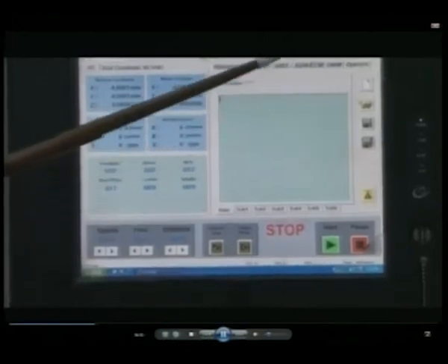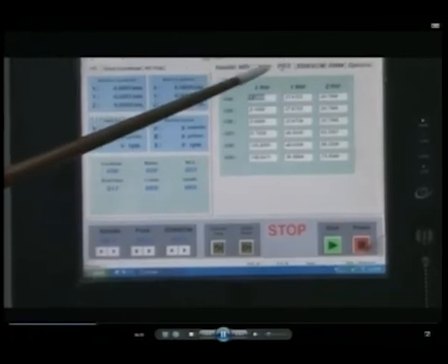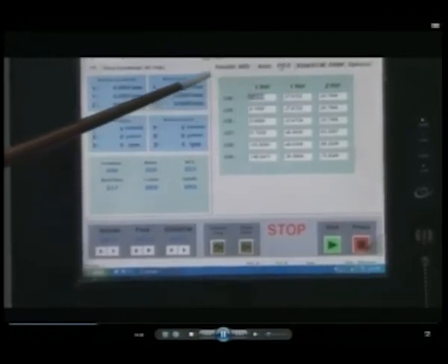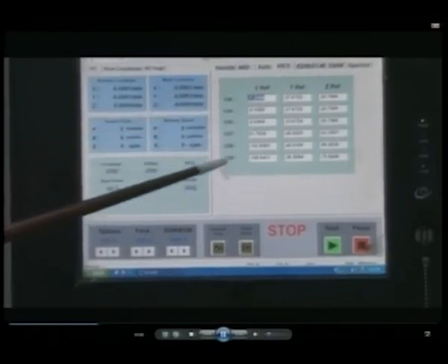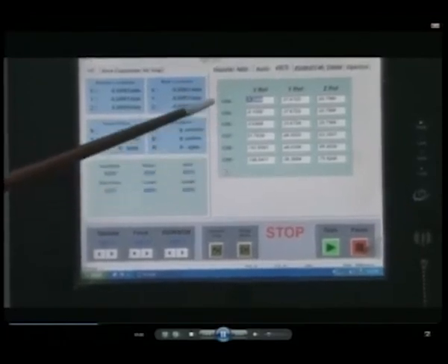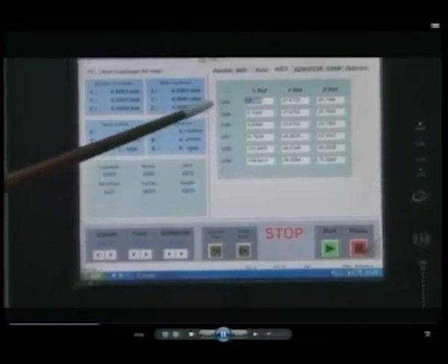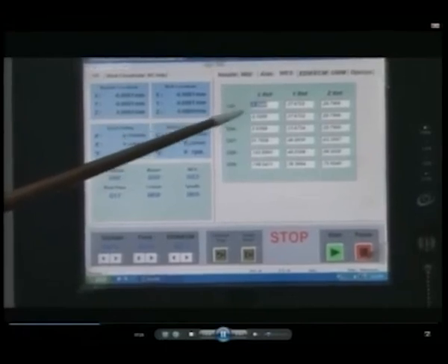The next window is WCS. WCS refers to World Coordinate System. In this machine, there is a feasibility of having 6 different origins on the workpiece. So the origins can be G54 to G59. Each G code will have a corresponding point called P1.